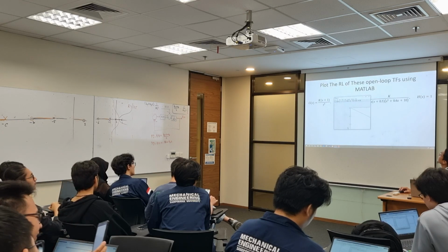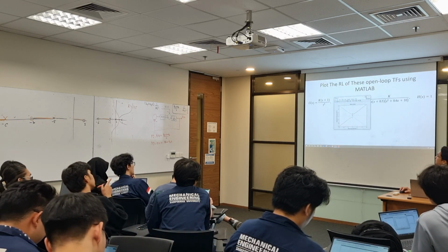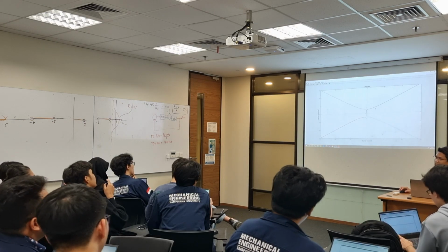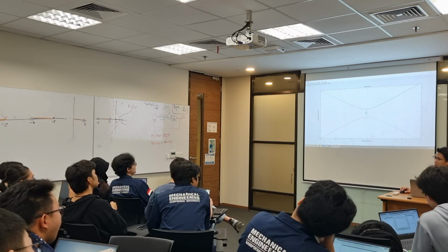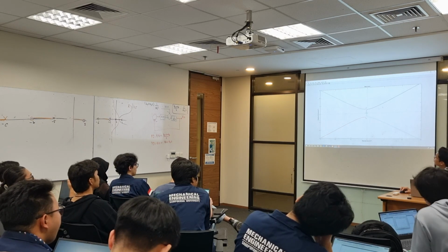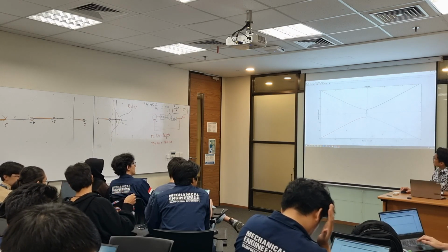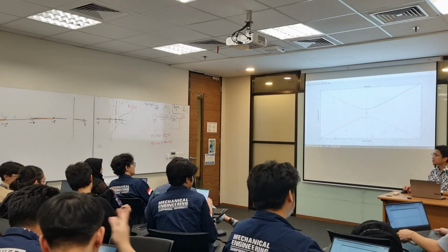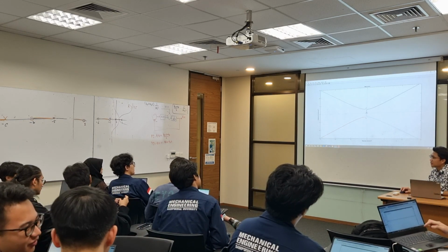That means there are 4 asymptotes, correct. If it is 4 asymptotes, the angle will be 45 degrees, 135. So is it stable or not? For some K, it is stable.